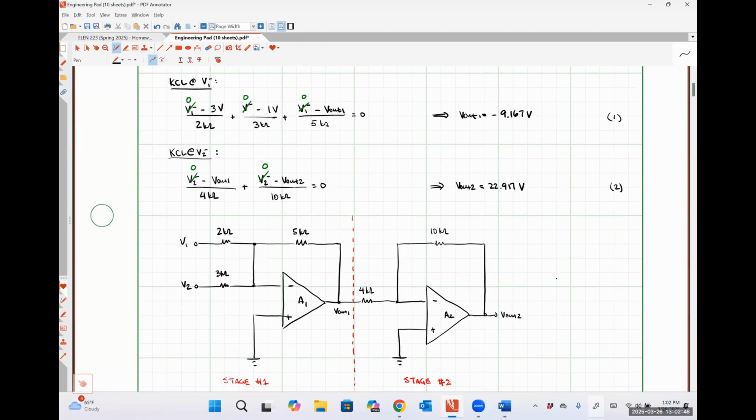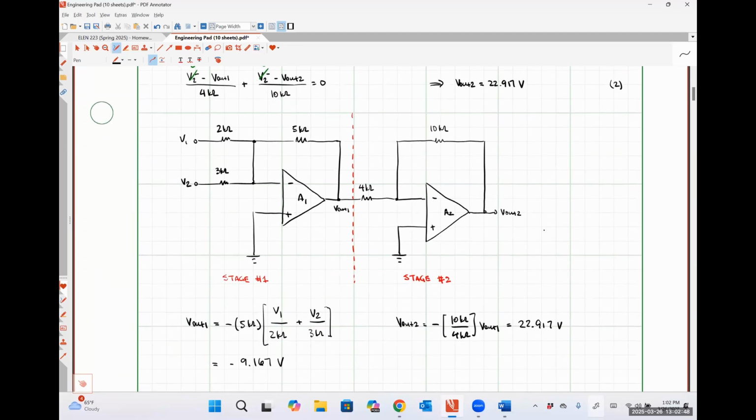The exact same result we got earlier. So this method of breaking the chain of amplifiers, or the cascade of amplifiers, into individual stages makes analysis of cascaded op amps incredibly simple, as long as you can recognize what each stage is. For us to be able to split into different stages, literally just put that dashed line on the output of each op amp